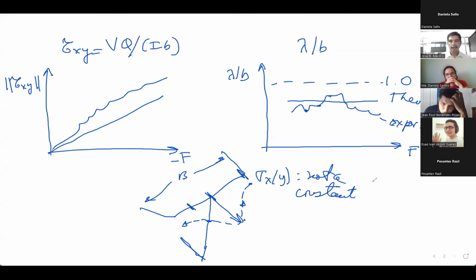Okay. Now here, what you have is effective breadth versus force. If you apply DNV theory, implicitly you are going to determine this value, because you have to reduce by this amount the effective breadth of the flange. So if you take this value here, you reduce this. So you reduce inertia. This is the mean value.